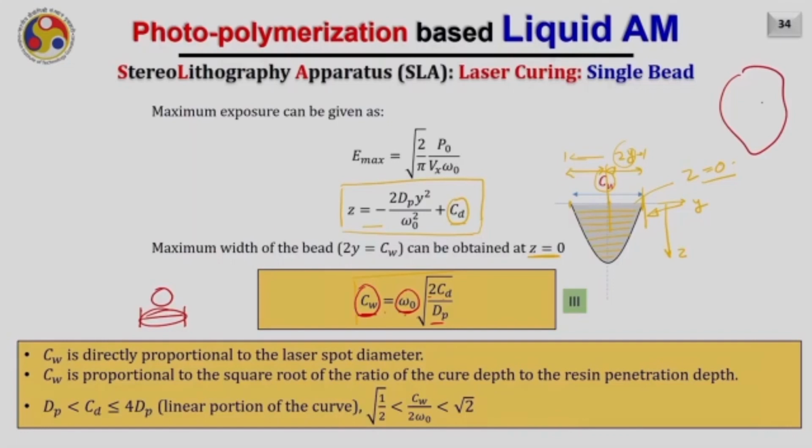The inside area of this contour is usually filled with a larger diameter laser beam, and the outer boundary is scanned with a smaller diameter laser beam, so that you can get a small bead width at the periphery and center, and the inside area can be filled quickly.